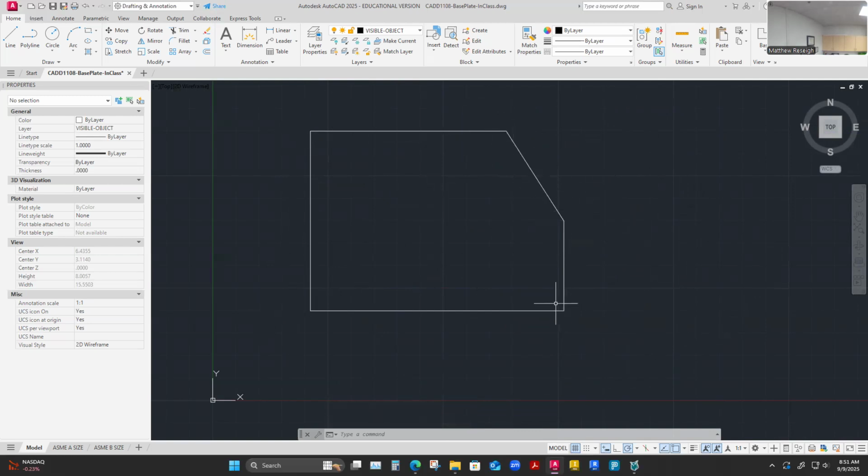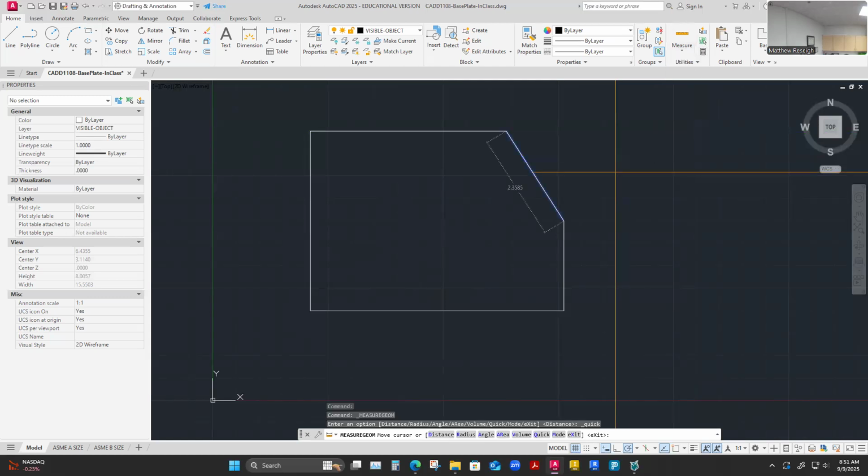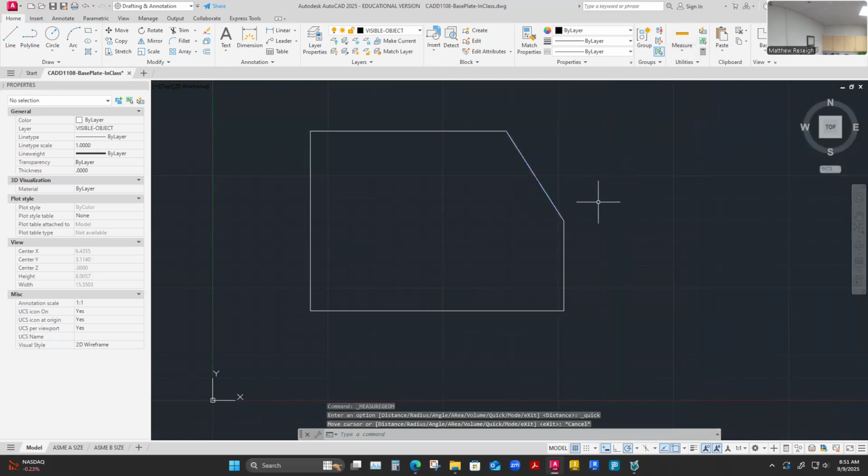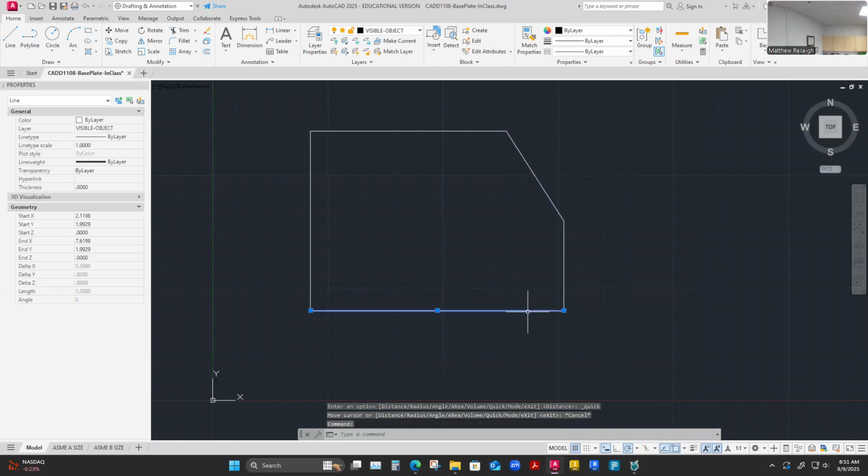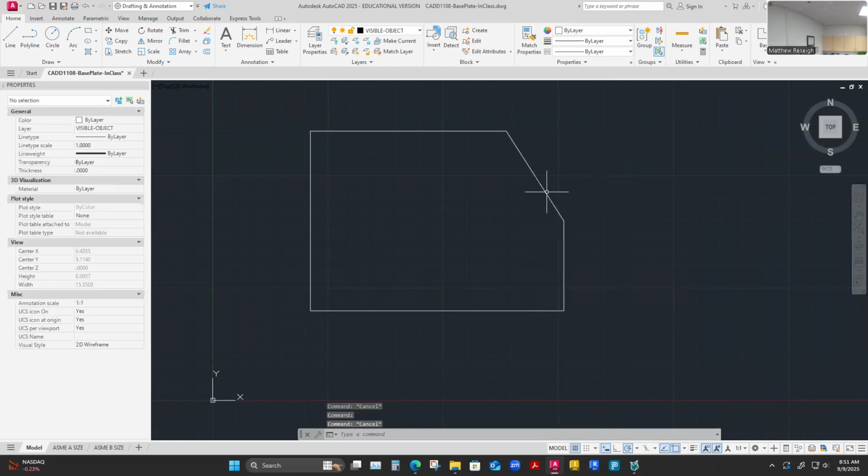And then as long as I follow the dimensions, I should be pretty close. Yeah. We'll double check. Excellent. Escape the check. This isn't joined. These are all single line segments. If I would have used the polyline command, this would have naturally joined into one unit, so one polygon. So I can go ahead and join that.